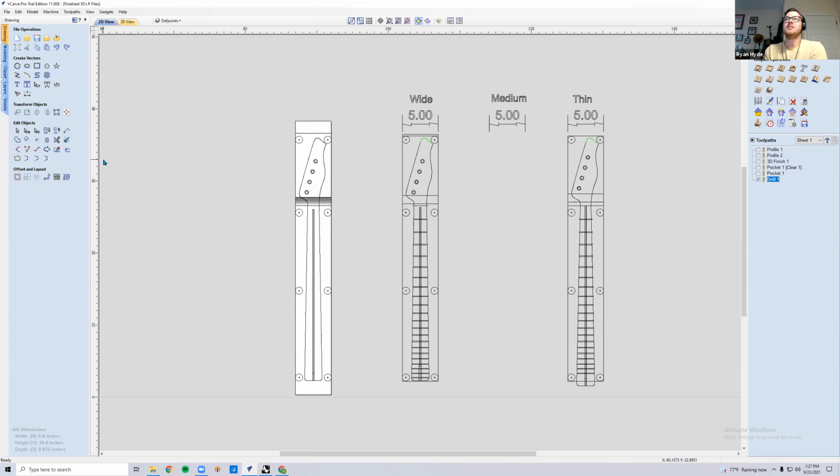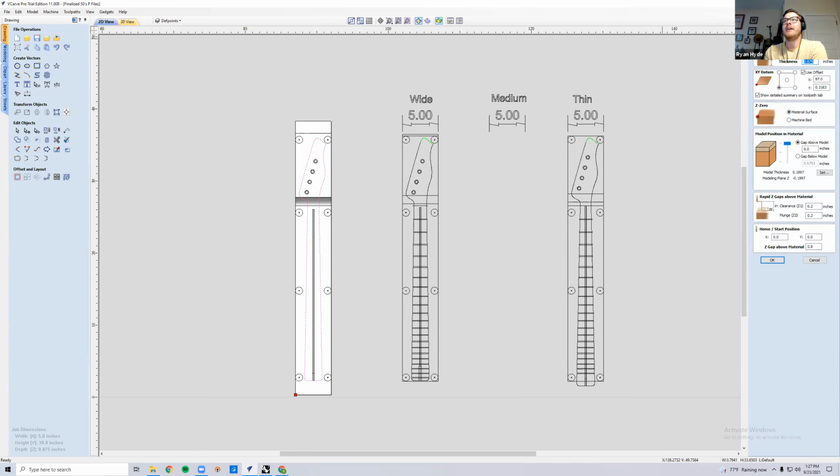To not destroy. So one thing that, again, the whole visual editor, and the other nice thing about this program is that if I'm doing something disagreeable, or say over here with my material, this is maybe a good place to start. I have my material set to 0.875, and I work in decimal often, and that's 7/8 of an inch. So that's some nominal jazz bass blank thickness. And that is literally the thickness of the piece of wood that I am going to mill and then put on the bed of the CNC machine.